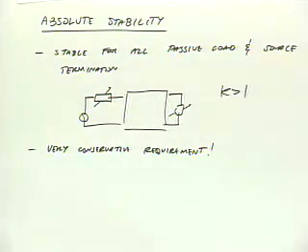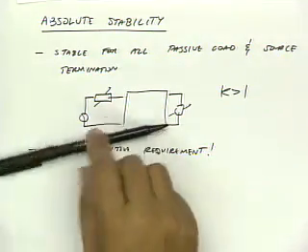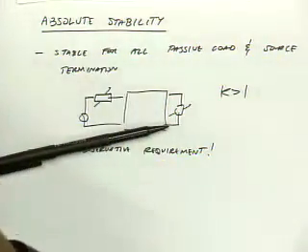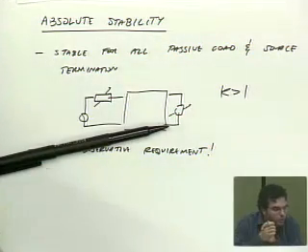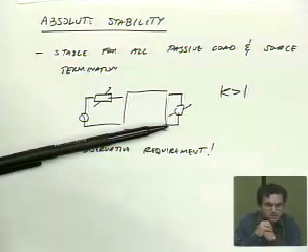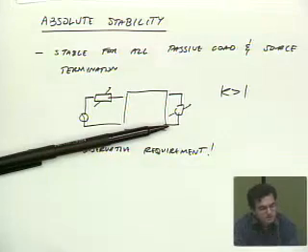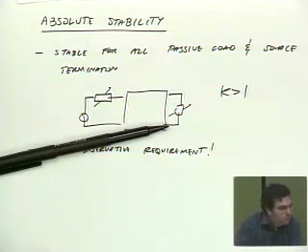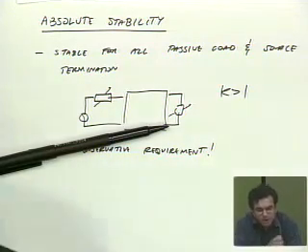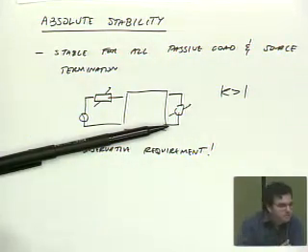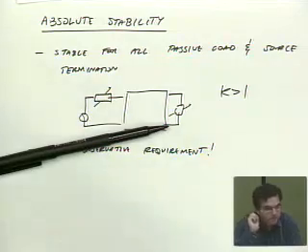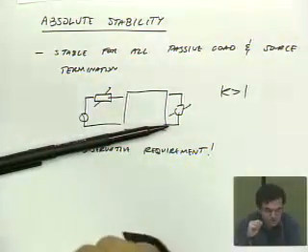because in practice the range of the load and source varies. So the idea is that if I'm designing an amplifier that I give to a customer and I say you can load it with anything you want, you can drive it with any source impedance you want, I guarantee it'll be stable. Then that means that k has to be bigger than 1. But then if I tell my customer, well, you know what, don't short the output. If you short the output, it's going to oscillate. Also, if you're driving it with a reactive source, yeah, it'll have problems.